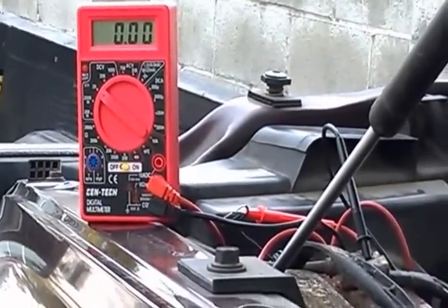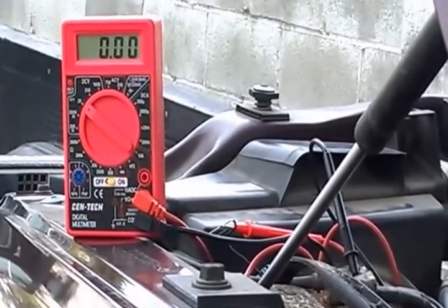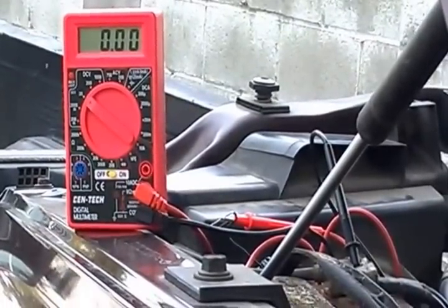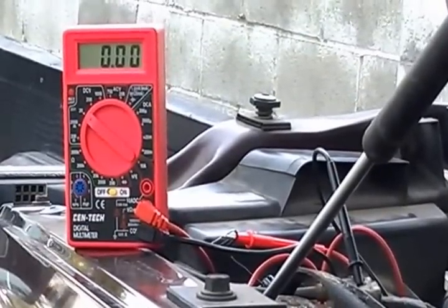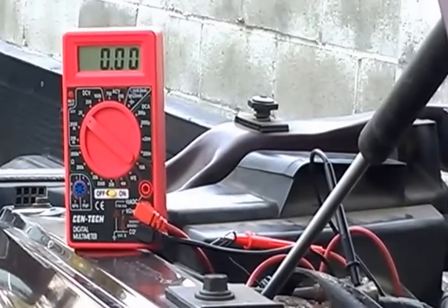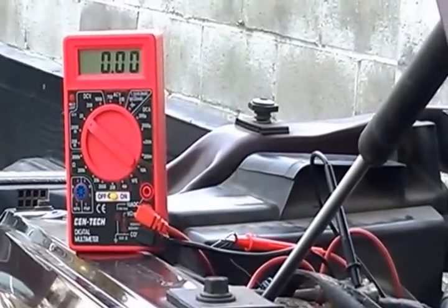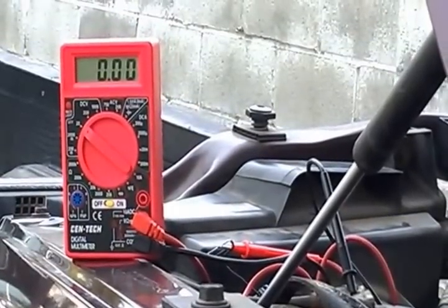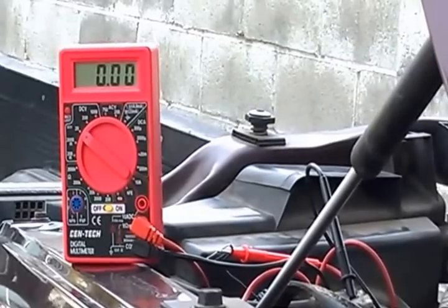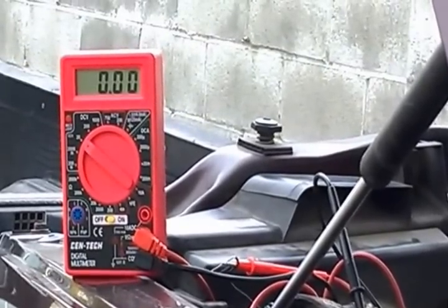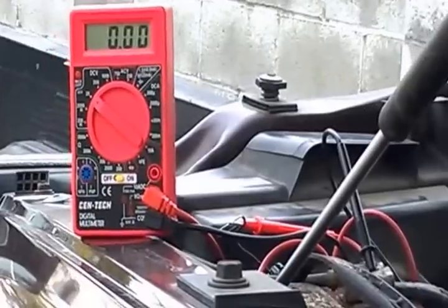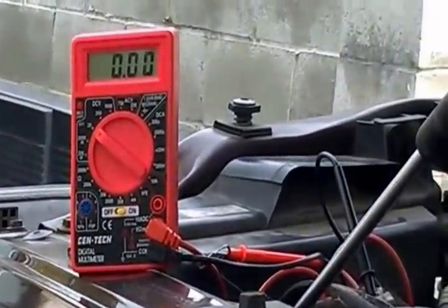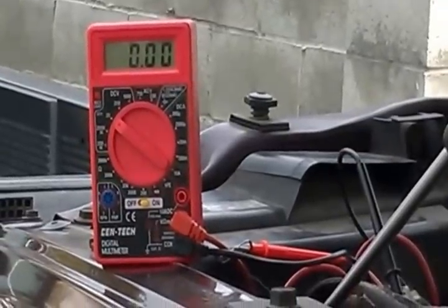As you can see, the max voltage was 0.42, but it did also vary. Like I said, this solenoid is being controlled pulse width modulated, so the ground side would also vary. In other words, don't expect a ground side voltage of 100 millivolts or less. So this shows that this computer is providing the power and ground.